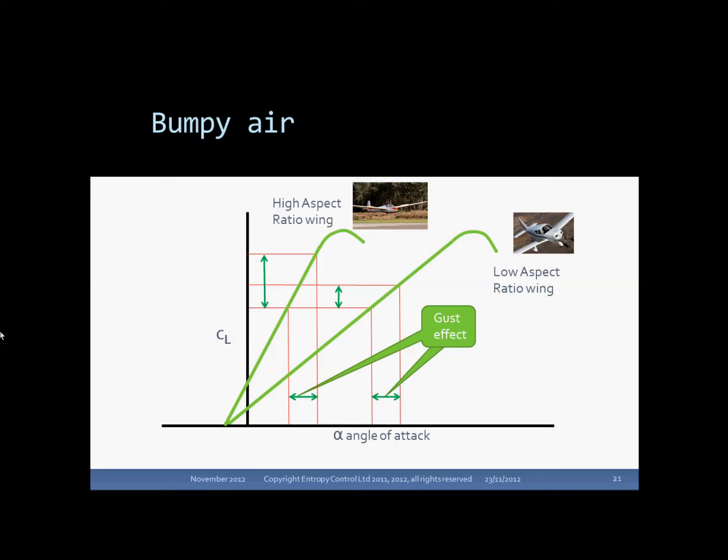To give you an example, the Piper Cherokee range, with its short stubby wing, has a reputation as a very stable IFR platform, while an aircraft like the Diamond DA-40 with its high aspect ratio thin wing is considered skittish. This difference is often attributed to differences in wing loading, but in fact the wing loading on the Diamond is higher than on the Cherokee. The relative skittishness of the DA-40 is entirely due to its high aspect ratio. And if you've ever flown in gliders, you'll know that they're pretty lively in rough air.